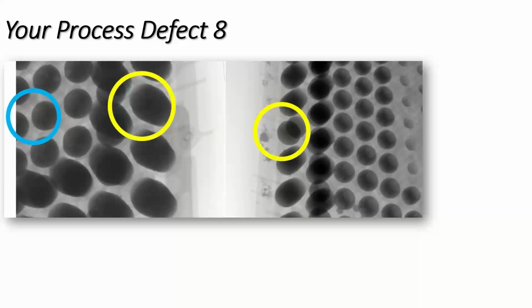But one of the problems that we have focused on in the past is warpage and open circuit connections, the end result being the issue that we talk about with head-in or head-on pillow. If you look at the example on the left-hand side, I've put a circle round it. First of all, the blue are the small balls on the bottom of the package, which is soldered to the board. And the one that's circled in yellow on the left-hand side is more like a column. It's 2 balls which have become liquid, and you get a shape which is more like a column.